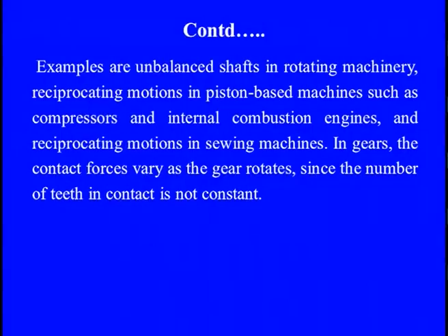So, with these, a huge amount of vibrations can be generated. Even in gears, the contact forces vary according to the gear tooth profile and the number of teeth, as the gear is rotating at speed. Because the teeth are continuously coming into contact, whether line contact, point contact or even surface contact, a huge amount of force is transmitted and a huge amount of vibration is generated because of the stiffness variation with the force transmission.